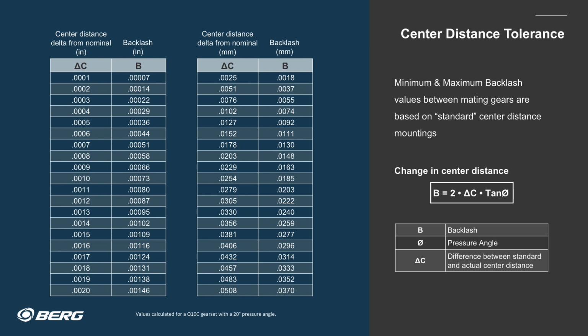When designing a gear system, here are some common practices for calculating center distance with given inputs. First, if you know the chordal tooth thickness of the gears and the pinion is fixed in place, the center distance at which the gears will mesh properly and meet the backlash requirement can be calculated. Alternately, if you know the center distance and tolerance, the chordal tooth thickness of the gears can be calculated. This can be compared to the AGMA quality information to select the appropriate gears for the system.